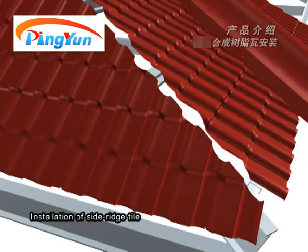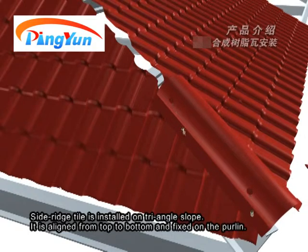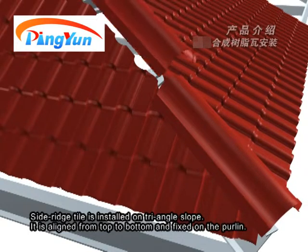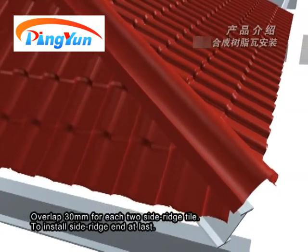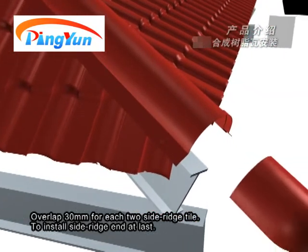Installation of side ridge tile. Side ridge tile is installed on the triangle slope. It is aligned from top to bottom and fixed on the purlin. Overlap 30 mm for each two side ridge tiles.